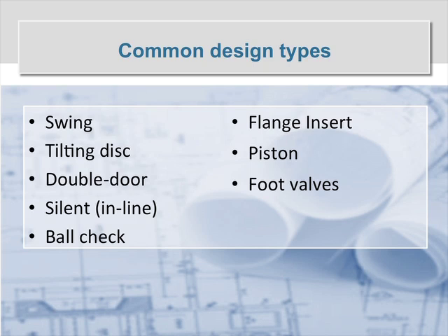But the one thing that check valves are not is a safety relief valve. That's a whole separate, unique style valve, purpose built and tested and certified for the purpose of protecting against system overpressurization. In this case, we're just talking about check valves that a little bit of pressure opens them up, and when that pressure stops, they close. I'm going to get into a little bit more definition of the more common types of these valves in just a second.